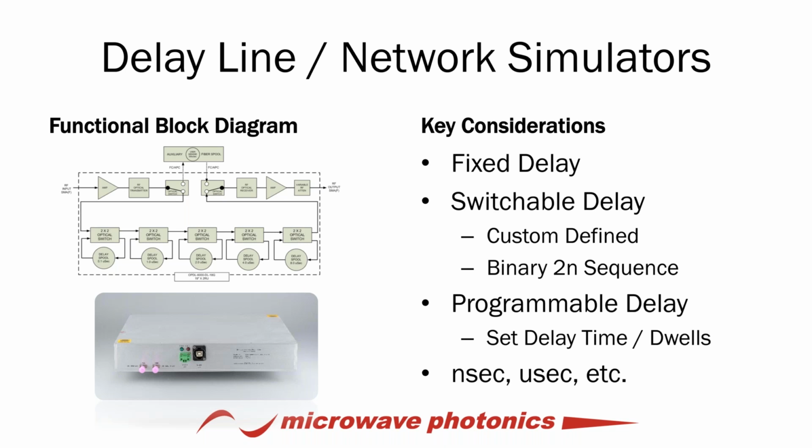Here in this functional block diagram, you'll see that we position an amplifier in front of a fiber optic transmitter. For this specific scenario, the rationale for that was to provide a certain gain, noise figure, input third order characteristic. And once we convert that RF signal to the optical domain, we have the ability to put that through a series of optical switches to impart the desired delay.